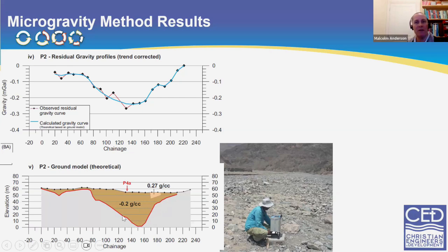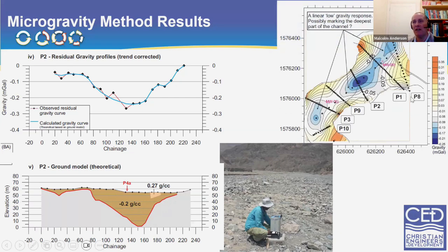And then the model calculates the differential reduction in density of the fill of the sands and gravel clasts. Now, most of these sands and gravel clasts are made from Precambrian rock, so it's the same rock, but it's the porosity that changes the density. So that's basically telling us you have a 20% porosity, which is pretty much bang on what you'd expect for sands and gravels. And then if you have a number of sections on them, you can produce a graph to show where the bottom of the wadi is and what shape it has.